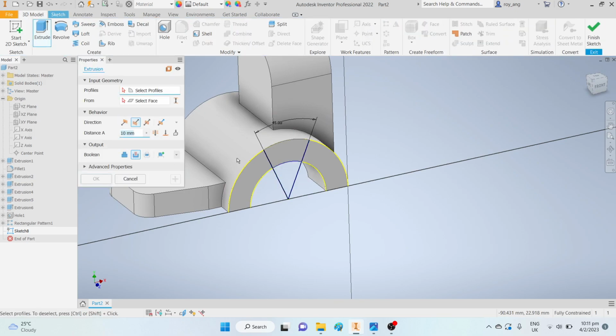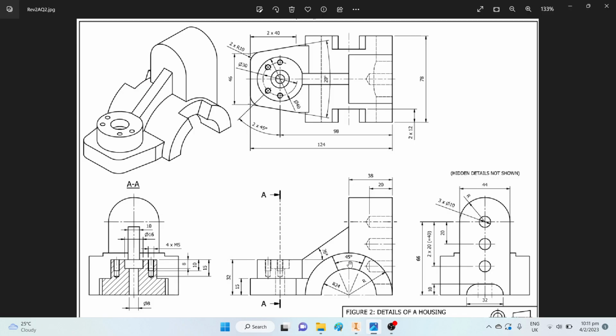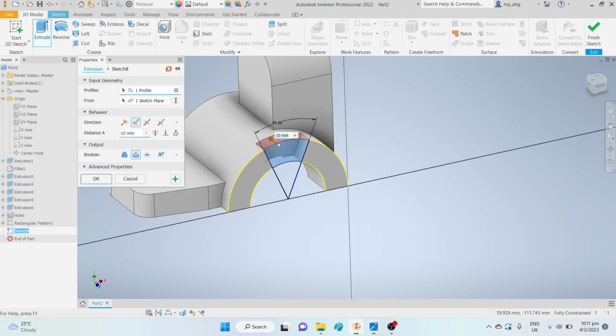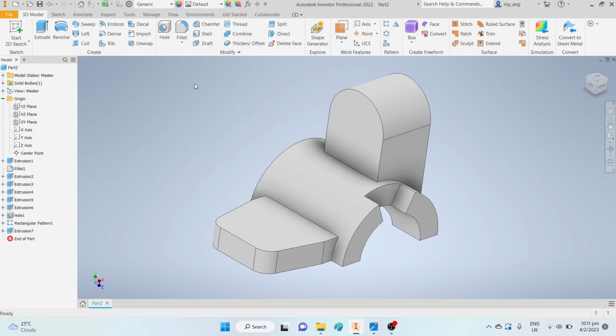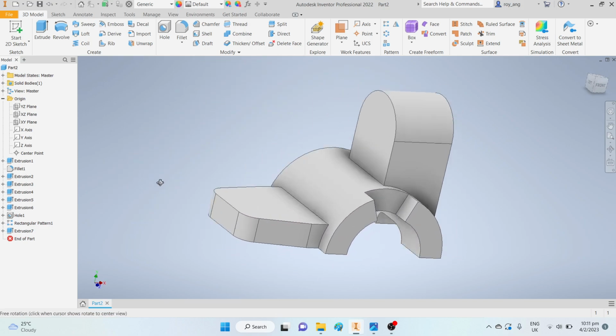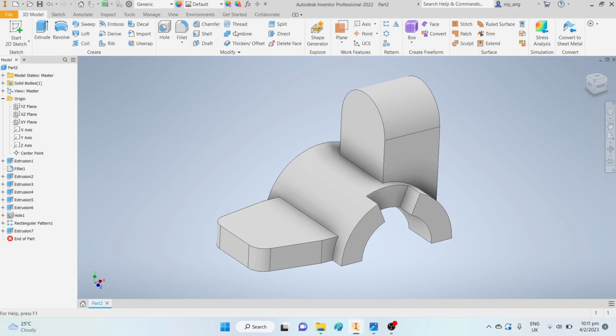Okay, extrude cut. You can select this region here, and the depth of the cut is, let's see, how much does it go in by? 2 times 12, so it goes in by 12 millimeters. Okay, now please don't repeat the same command on the other side by drawing it, because you will lose points for not using the mirror command.